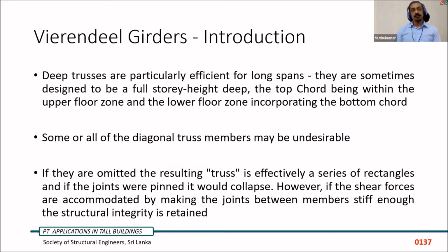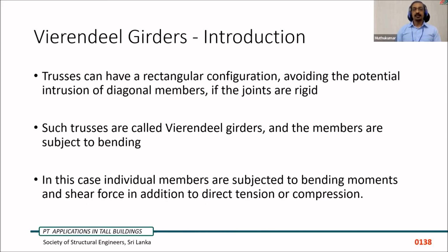Sometimes it is designed to be full story deep. The top chord will be connected to the top floor and the lower floor will be connected to the bottom chord. Diagonal members are not always preferable, so we will try to omit them. Functionally, we can pass some services in between the verticals.